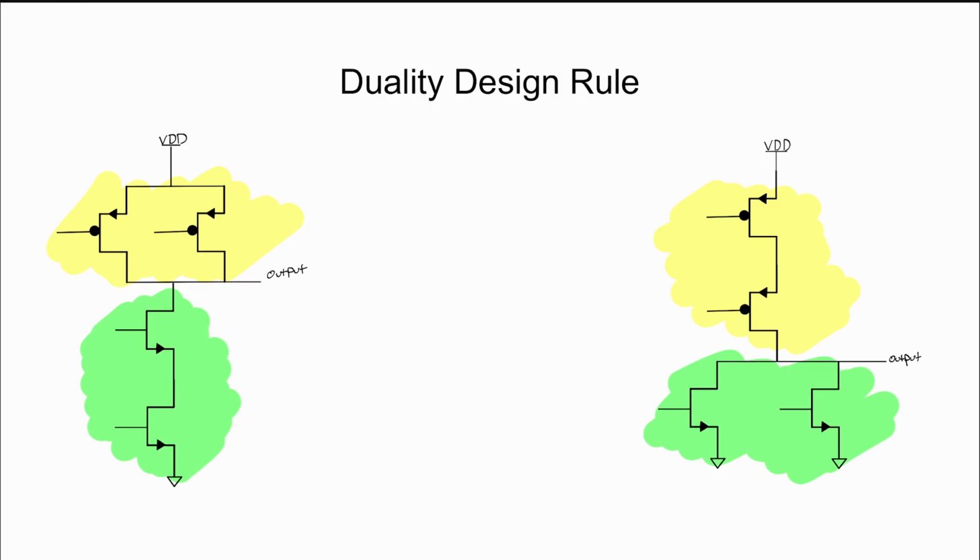It's also worth pausing on why the pull-down network is always NMOS and the pull-up is always PMOS, never the other way around. NMOS is excellent at pulling a node down to a solid 0 volts, but it's bad at pulling up. As the source voltage rises, VGS shrinks, and once it drops below the threshold, the device just shuts itself off, stalling out short of a full VDD.